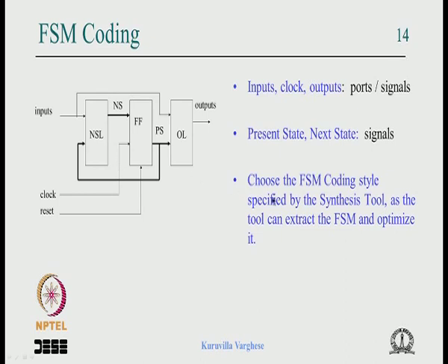So it is very important that when you work with the tool, you refer to the tool manual and find which coding style is specified by the synthesis tool, and stick with it and don't try to code it in any other way.